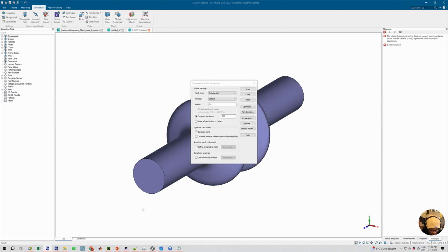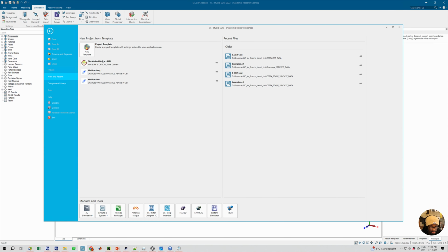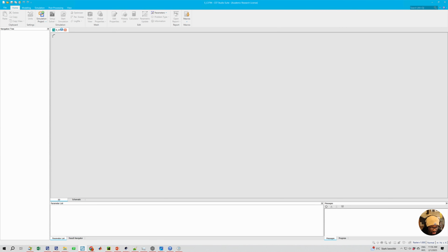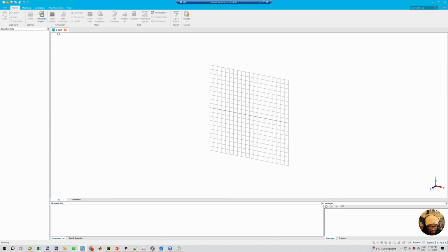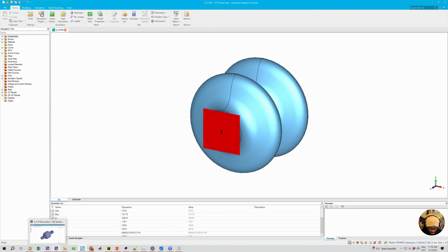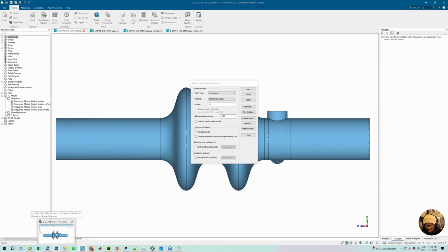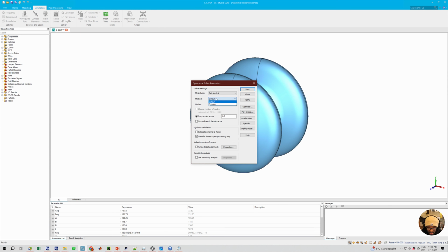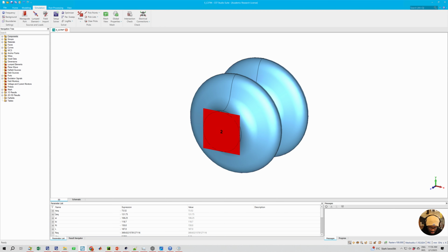Now if you go to 2020, which I haven't checked. I hope it opens on time. Okay, yeah, just a test project, and while that loads, I also checked 2025. 2025 is consistent with the 2023 version. So what you have in 2025 is classical lossless and also lossy. Now in 2022, for the eigenmode solver, what you have is default and preview. Default is the lossless and preview is the lossy. So that's it. I don't think I have any other versions.